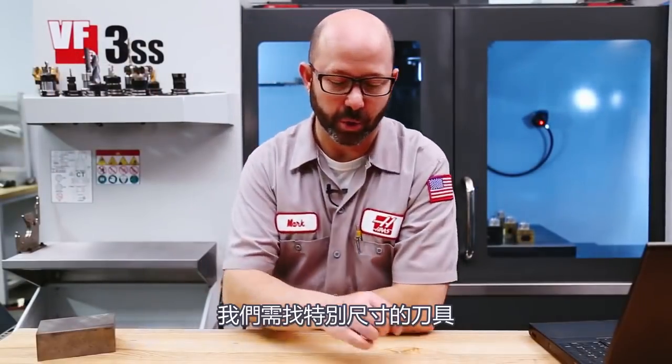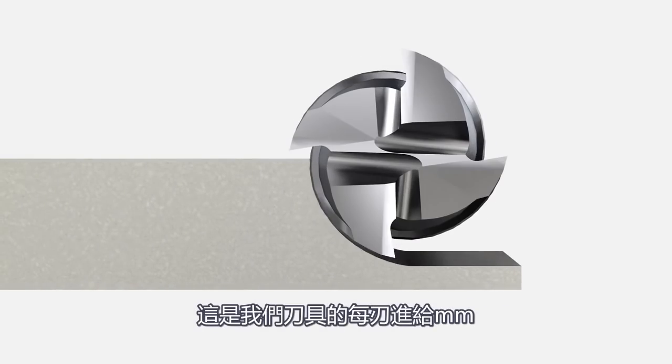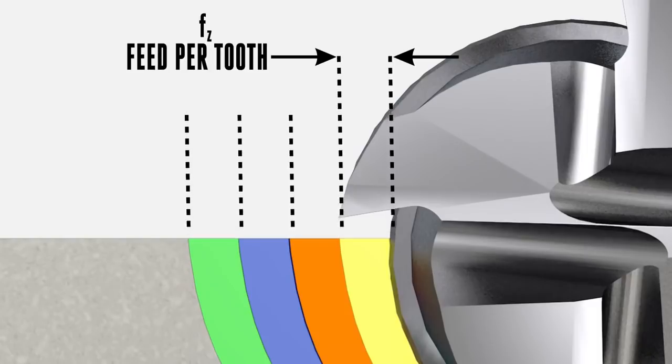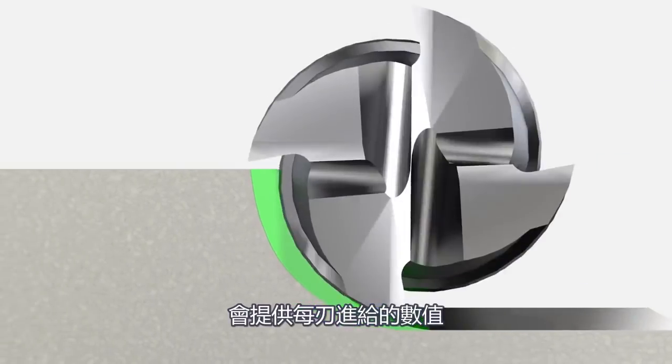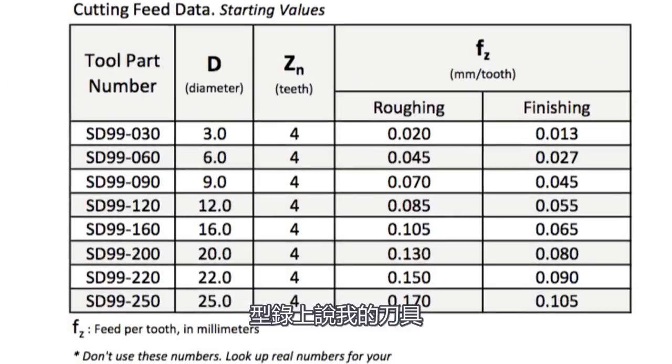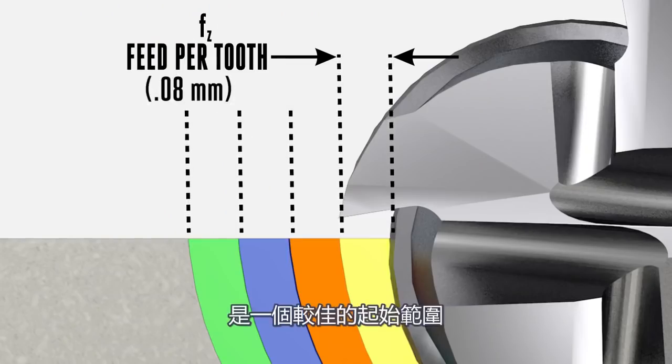We want our tool to take a very specific size bite with each tooth. This is our feed per tooth in millimeters. Just like our cutting speed, the book, or PDF, will give us that feed per tooth value. The catalog says that for my tool, material and type of tool path, 0.08 millimeters per tooth is a good starting range.